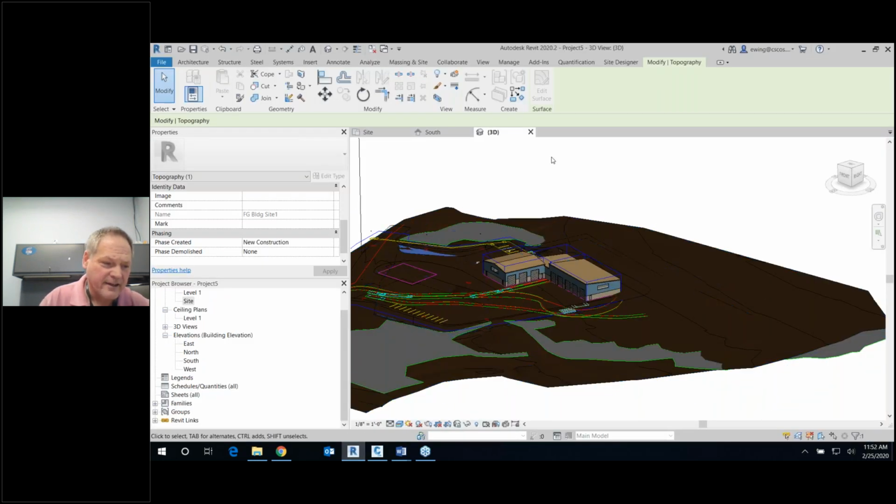And since you're coordinating it, many times our landscape architects will be working with the civil engineer in the Civil 3D model, right? Adding those subregions and stuff. So we don't have to keep adding subregions in Revit, because now that we're coordinated with the civil, any work we do on the Revit side is not going back to that civil model. It's going to get overwritten, right? So once you're coordinated, it wants to come from that Civil 3D side of it. Fortunately and unfortunately.